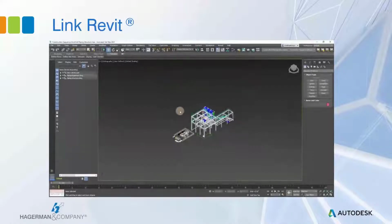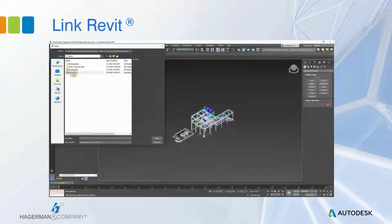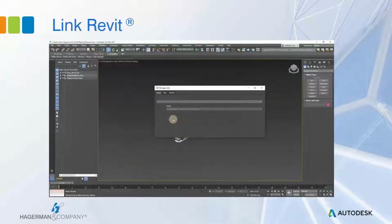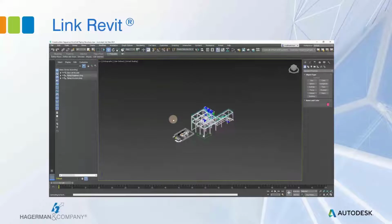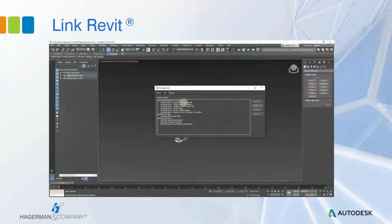All right. Next, we'll bring in the Revit project. This will also be a link. Revit also comes with some presets that we can leverage. And we are going to look at one of those here. That way we can group things the way we want. We can also choose which view from the Revit project that we want to bring in. And for the presets, I'm going to duplicate one of these. I like to group things, doors with doors, walls with walls, and so forth.